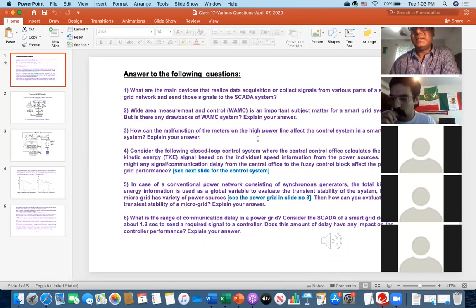So therefore, throughout the smart grid network or microgrid network, lots of PMUs, RTUs, and sensors are placed. Those are continuously monitoring the system. They are gathering various data like voltage data, power data, frequency data, reactive power data, speed signals, or any change of system behavior, and they are sending it to the SCADA.